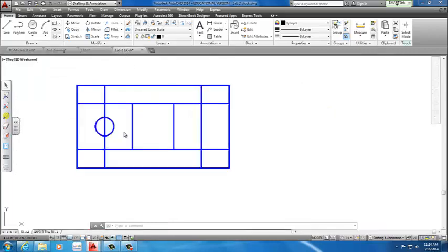There's two places. Fillet, R for radius. So we select this circle. We type in R, enter, and you type in it. Instead of drawing another circle, we're just gonna make a copy. So you go to copy command. 1.62.